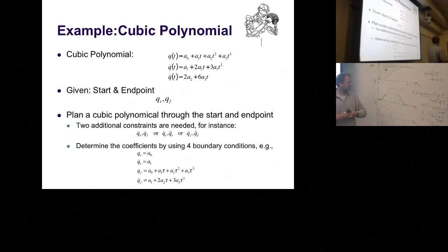Now, this cannot be represented, for instance, by my cubic polynomial anymore, also not by my fifth order polynomial, since this is just too complicated a curve. And you have 2 choices now. You can basically make this longer, add more coefficients, and somehow code that point as the intermediate boundary condition, which is at a particular time.